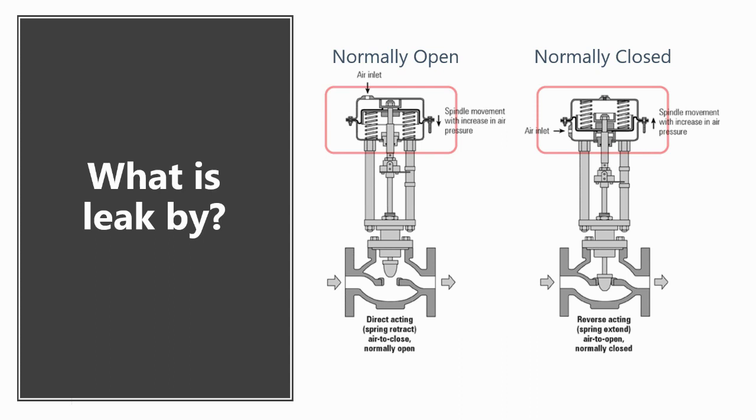On the other hand, the normally closed valves use an actuator with an internal spring designed to keep them shut without needing the actuator to work to hold the valve firmly seated. Chilled water valves are usually normally closed type of valves. They're dependent on the control signal and the actuator to drive them open when cooling is needed. Without a control signal, or if the actuator fails, the valve remains in the closed position.